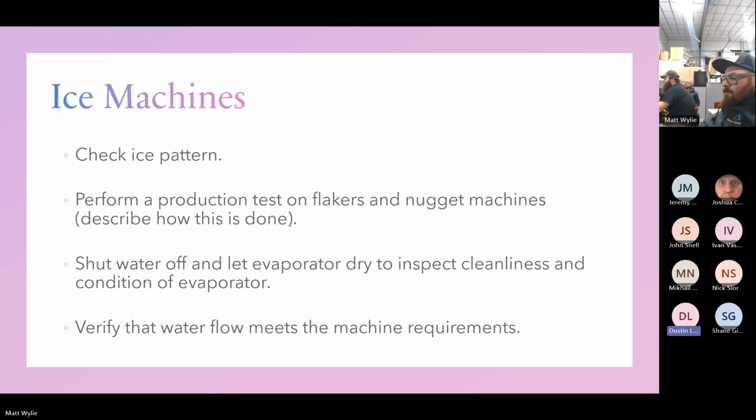Does anyone know what I'm talking about? It's like a honeycomb. It's usually metal. It's part of the case, and it goes the entire length of the case, and it's got a bunch of little holes in it. And those holes love to get filled with dirt. So if it seems like you cleaned your honeycomb and everything seems to be working good, but your airflow's weak, or you're just not getting the airflow that you need, or your air curtain's not strong enough.